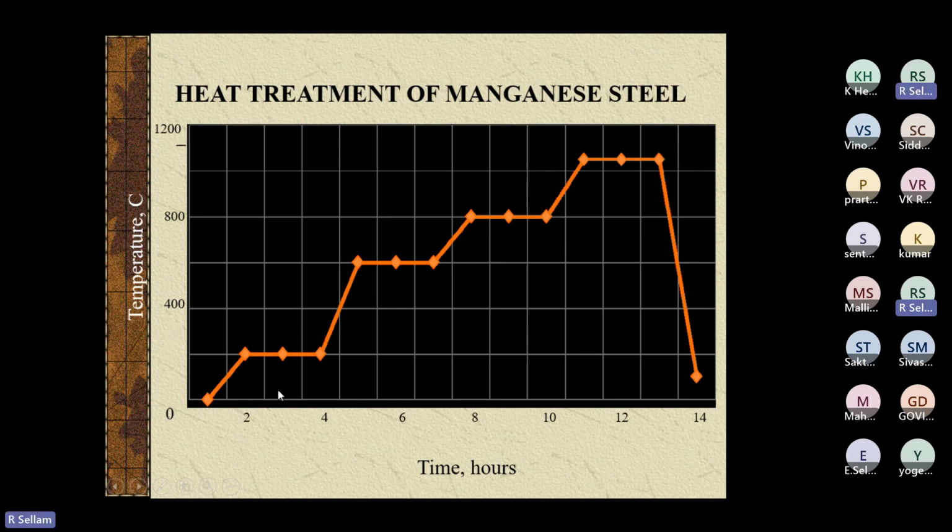But if you adopt our process, you reduce the volume fraction of carbide phase. You can insert directly at a higher temperature, so that the thermal stress will be less, because of the higher volume fraction of austenite phase, which will absorb the thermal shock. So you can reduce the thermal cycle drastically, but I cannot say it is done on an industrial scale.